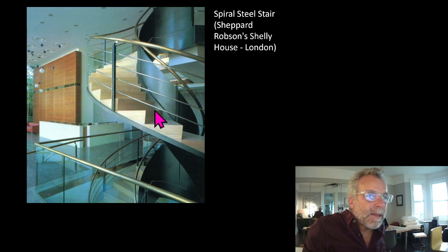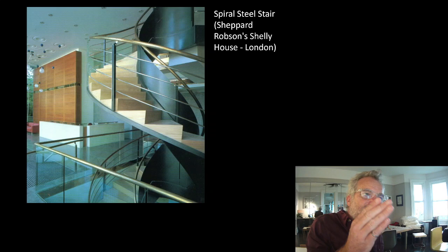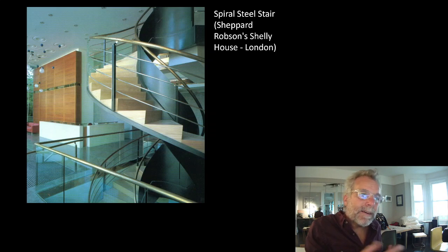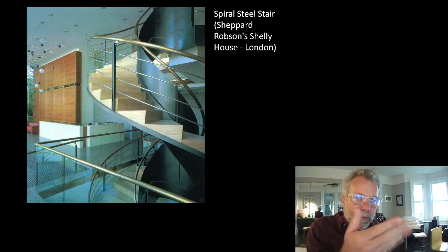Another spiral stair, cantilever treads with a very thin edge. You can see what they've done here. This is actually a box section down at the bottom. The stringer is a box, then up above is a plate. Now, this is interesting. A plate structurally cannot carry an awful lot of load, or essentially zero load. Under any kind of compression, a thin plate like that would just buckle.